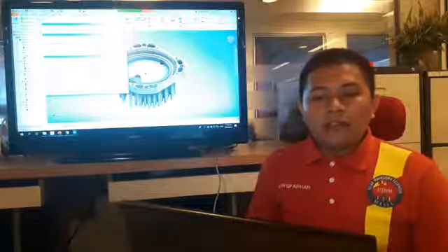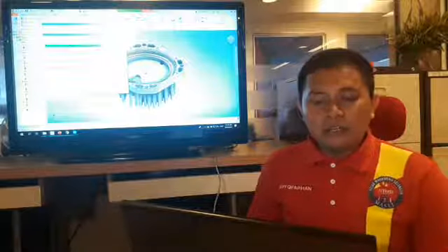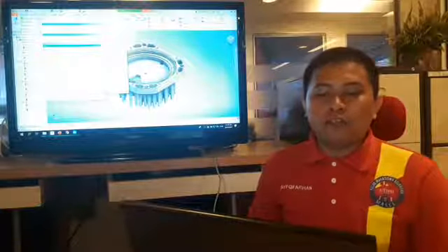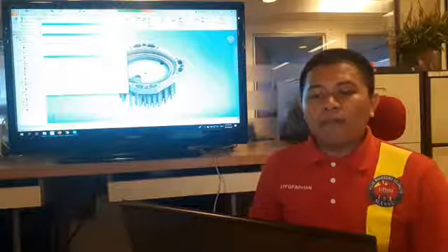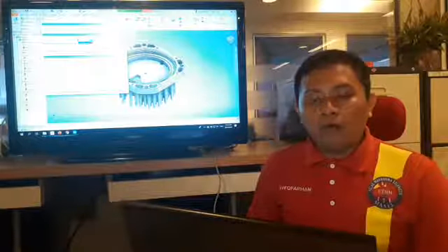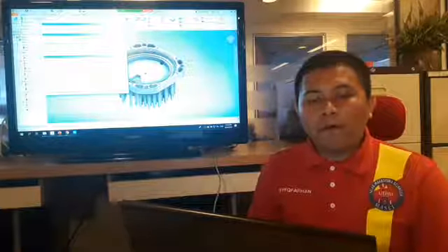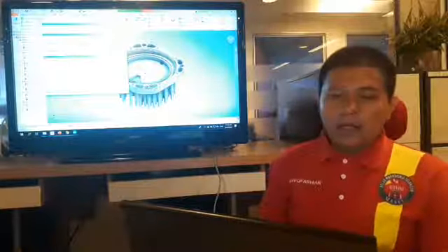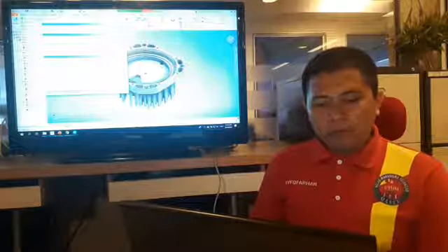Okay, the things that I need to set is the machine that I want to choose. For example, I choose the Mitsubishi setup. So all vendors, I just let it become all vendors. And for the machine, I want to choose the milling machines over here. And the program code, for example, this one, I make it 1122. Okay, so by default,